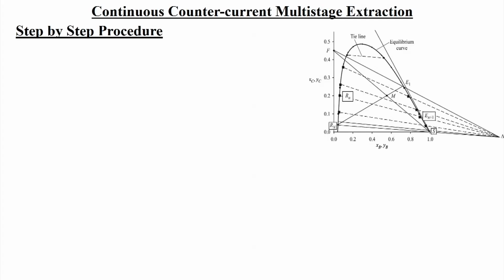If we know the extracting solvent, carrier solvent and solute miscibility, then we have this ternary diagram. We will now draw it from the equilibrium data points, and we will get the binary phase zone by drawing the equilibrium line. Suppose this is the plait point. The left hand side will be the raffinate arm and the right hand side will be the extract arm. This is common to every extraction stage. So, now we have to draw this ternary equilibrium diagram.